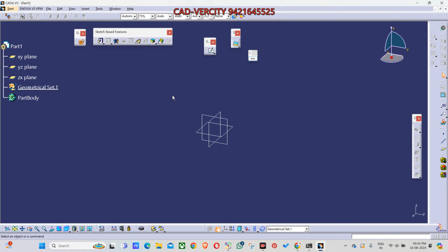What we will do, we will learn one command, the position sketch. So for now, how can I hide all these three planes in one shot? How can I hide this in one click? What I will do, I will click over here, hold the left button, and drag my mouse like this. I have selected all three planes. And what is the shortcut for hide and show? What is the shortcut I have set? Quickly, space. Got it?